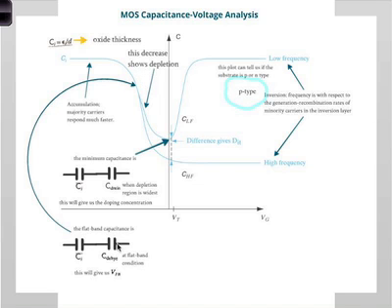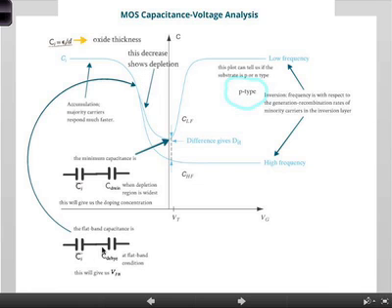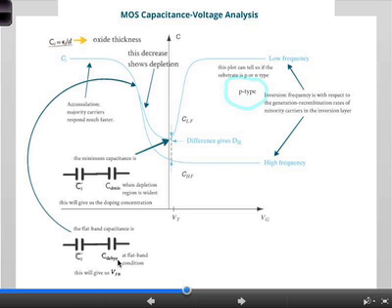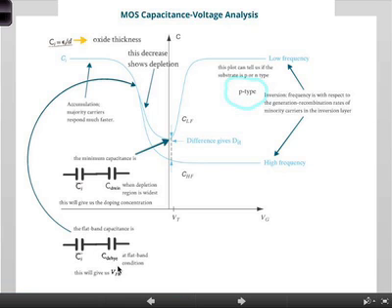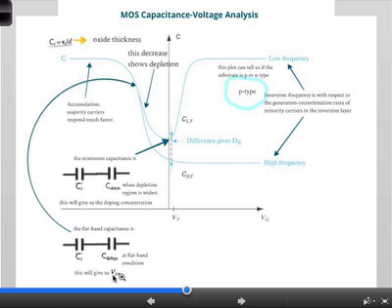And in that case, you get capacitance, which is from the depletion region, which is referred to as a Debye capacitance, which has to do with the screening Debye length. But again, less important for our conditions. But by looking at this flat band condition, we can calculate what the flat band voltage would be. Okay?